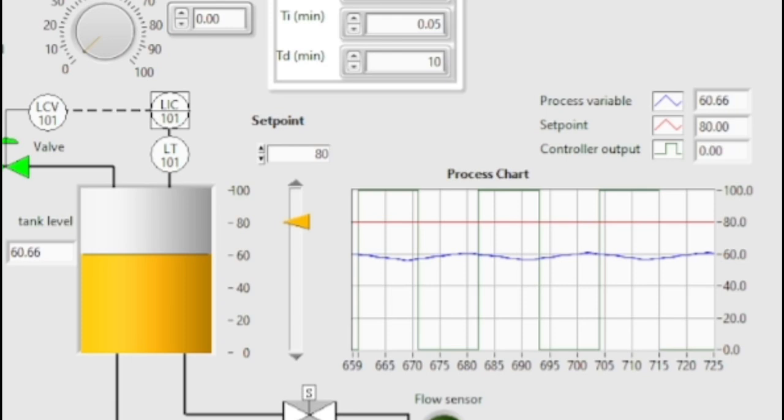So this is the maximum value that I get, which is 0.66. As you can see, the value of PV cannot reach the set point value. This is because the PID with large TD reduces controller output too much and too early, causing the inflow to be insufficient. Even at 100 output, the inflow cannot overcome the leak, so the system stabilizes below set point value.